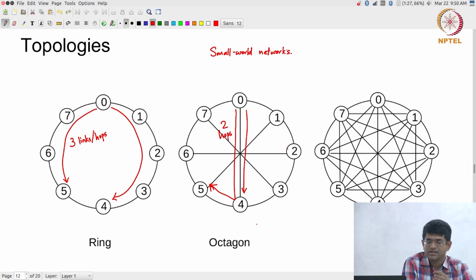The point of these small world networks is, even though you have a very large number of points that need to be connected, there are some long range links, okay, which suddenly end up making 2 different parts of this set of points that you want to connect come close together, okay. That's the kind of thing that you are trying to solve in the network on chip. You are not necessarily interested in finding a very regular structure, or ideally you would like a regular structure, but you are thinking of ways by which I can quickly get to my destination. So if there are a few long range links, right, they might allow me to make use of them if I actually want to go across large distances in a shorter number of hops, right.